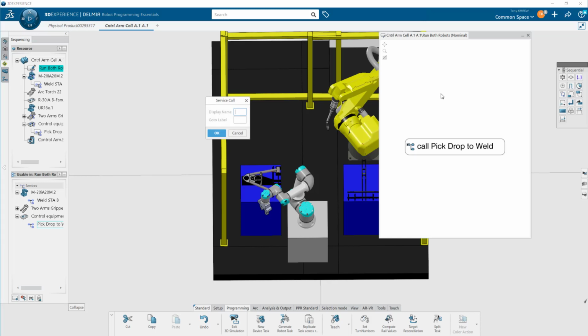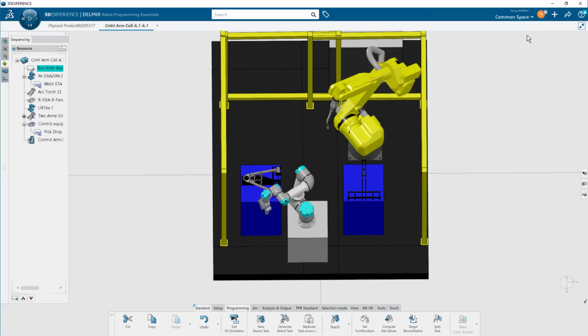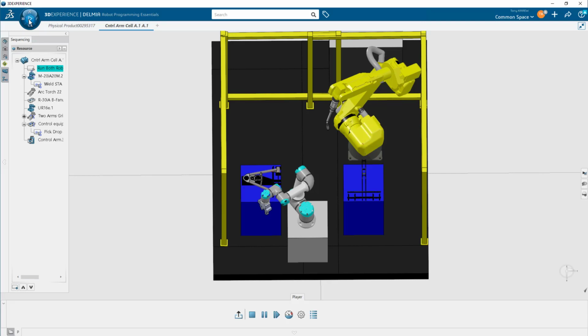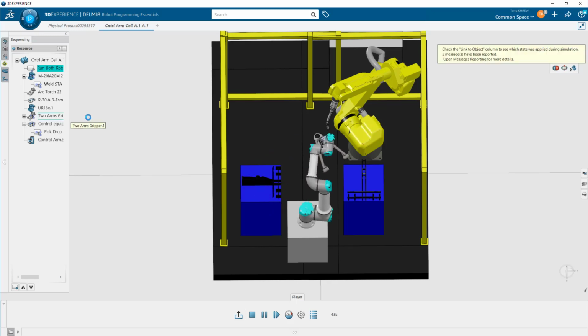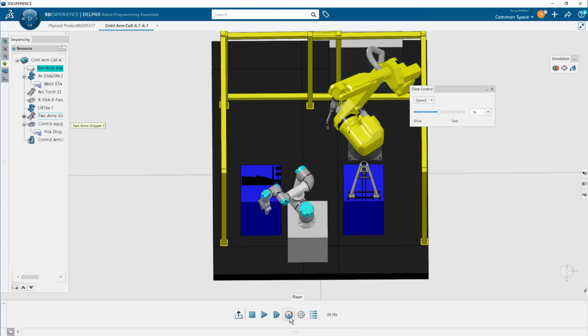So if I drag and drop the universal robot task and I drop it in this window, and then I drag the FANUC program and drop it in this window, it sequenced them automatically. So I just drag and drop, and then I'm done. So now when I run this task that belongs to the station or the cell, it will sequence them and the universal robot will go, and then the FANUC will weld. So pretty simple to sequence them using this editor.